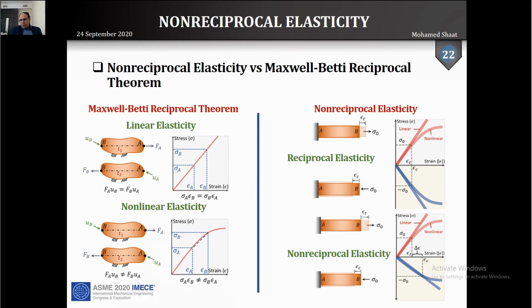Mechanical systems that achieved non-reciprocity by breaking the time reversal symmetry mainly depended on active materials, like the robotic and gyroscopic materials that I just presented. The non-reciprocity achieved by these active materials is, by definition, dynamic non-reciprocity, and these active materials cannot achieve any static non-reciprocity. Static non-reciprocity requires a passive material that is capable of breaking the material deformation symmetry, but remember, this should be done under the same kinetic condition.